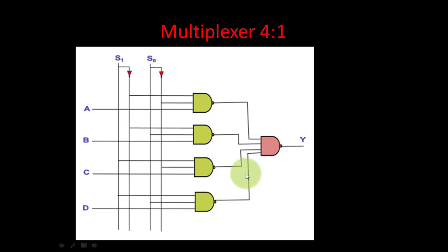Before understanding the working, we must understand that the output of a NAND gate is high when even a single input is low. In this case, for the green NAND gates there are 3 inputs. If a single input becomes 0, the output becomes high. We don't need to see the other inputs. Only if all the inputs are high does the output become low. So to make the output of a NAND gate low, all the inputs should become high.